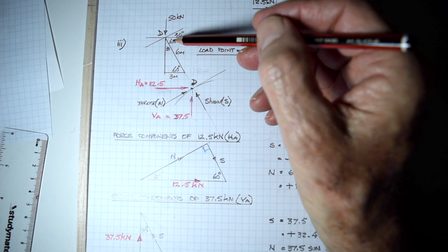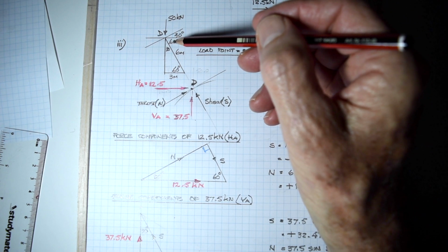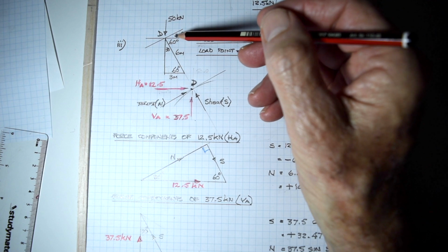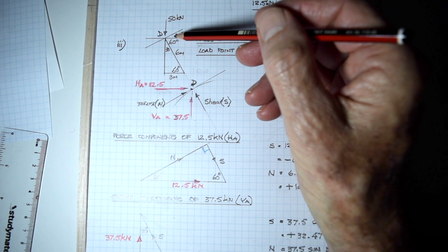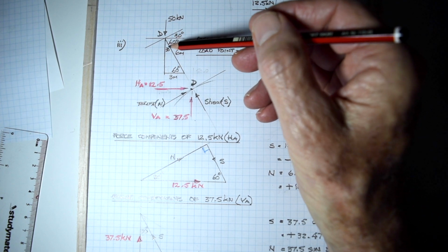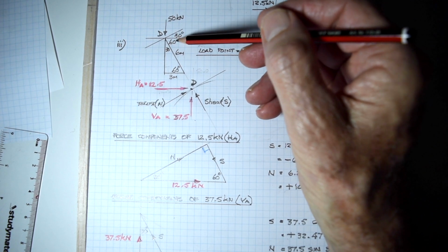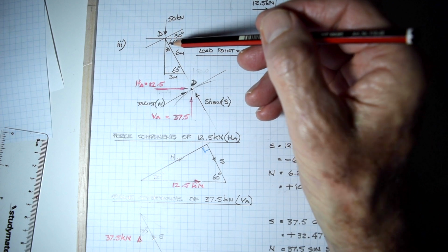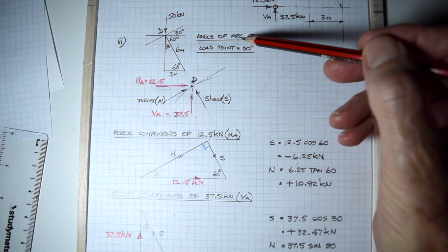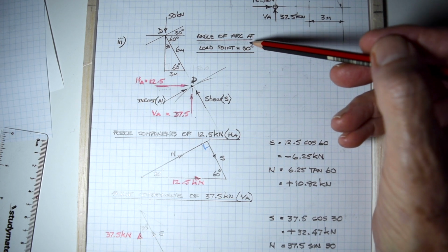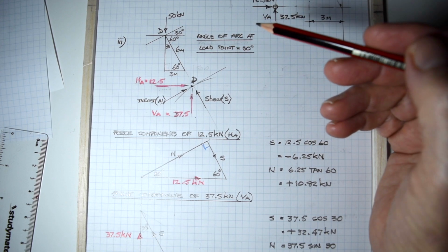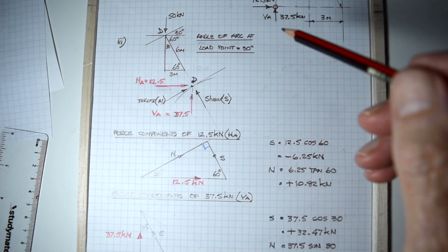And the two interior angles of parallel lines are 60 degrees. From that we can compute this. It's 30 degrees. Okay? Because that's 90 degrees, that's 60, that's 30, that's 90 degrees there. So the angle of the tangent to the arc at the load point is 30 degrees. Quite easily done.